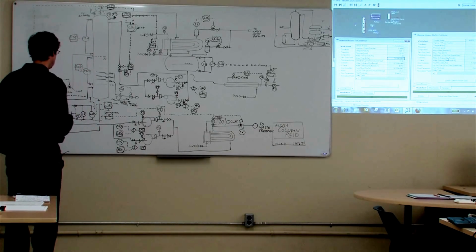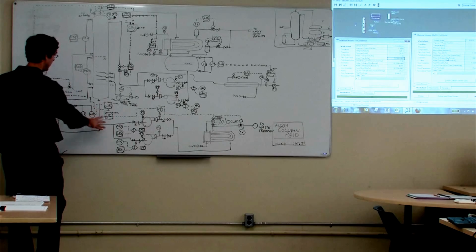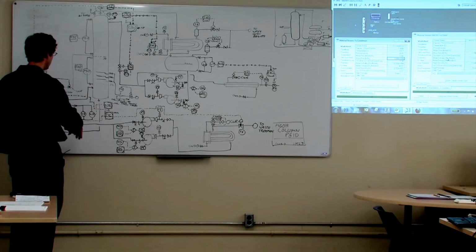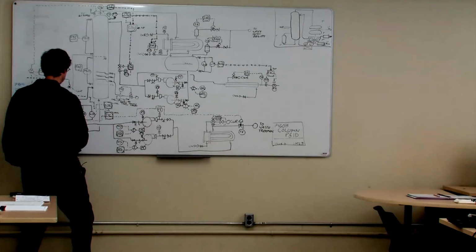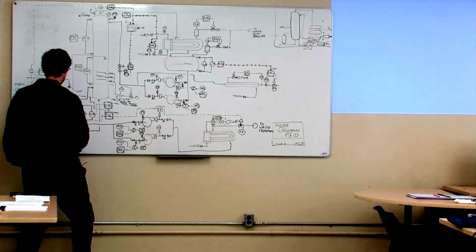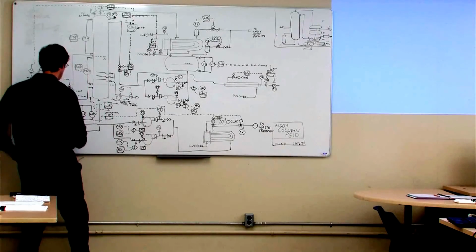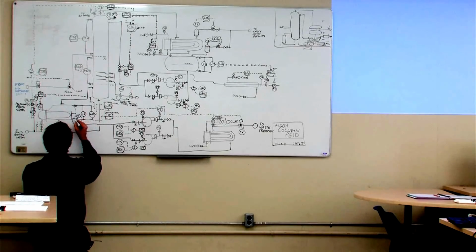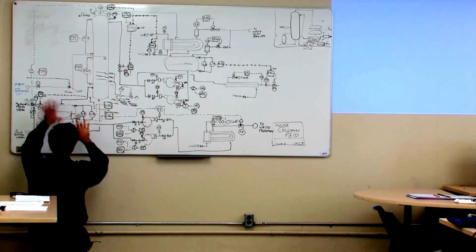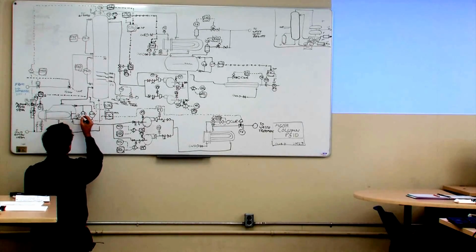Okay, that's good. We're missing a couple of interlocks maybe down here in terms of the level. So if the level transmitter has failed, we might be smart to have a level switch down in here, probably off a separate tap. So let's put that in, and I really have no space down here at all. So I haven't planned ahead very well. That's a problem with trying to show stuff on kettle reboilers. It's easier when you do it on the tower, but okay, so let's just kind of draw this.